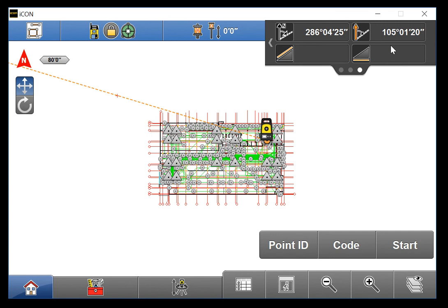The final page presents us with more advanced information. The upper left box contains the horizontal angle right turned by the total station from its base angle to your Prism rod. The upper right box contains the zenith angle turned by the total station from its vertical plane to the point it's currently measuring. The lower left box contains the slope distance, or hypotenuse, currently being measured. The lower right box contains the horizontal distance, or adjacent side, currently being measured.